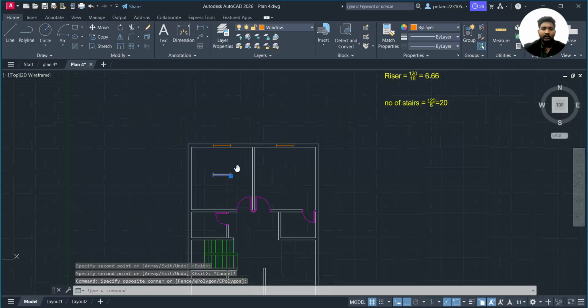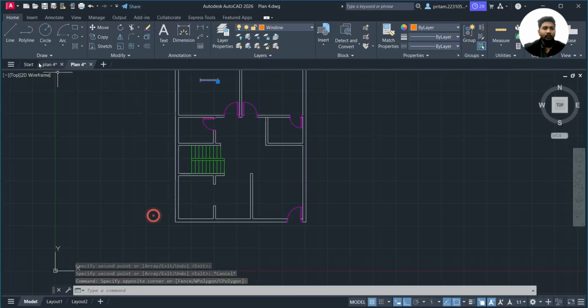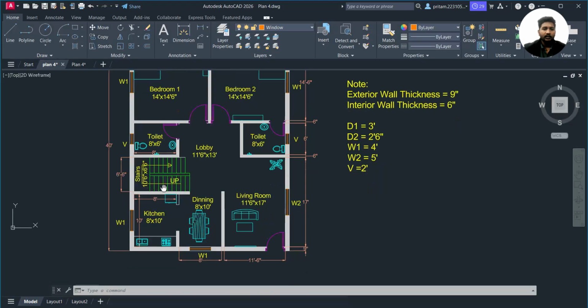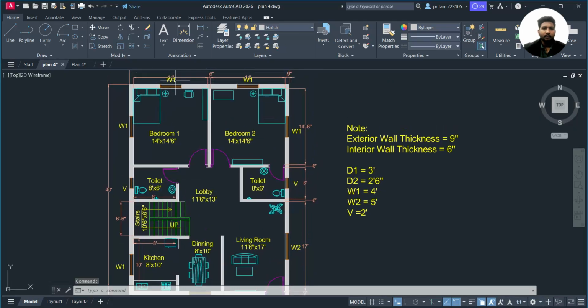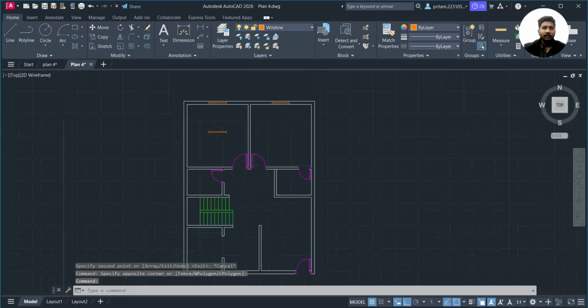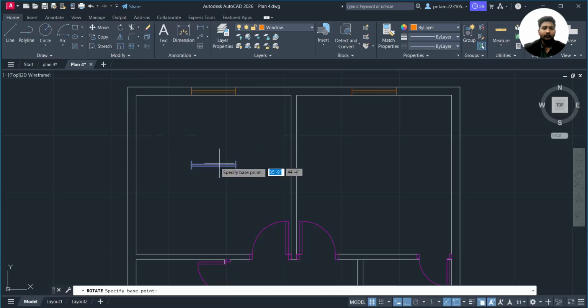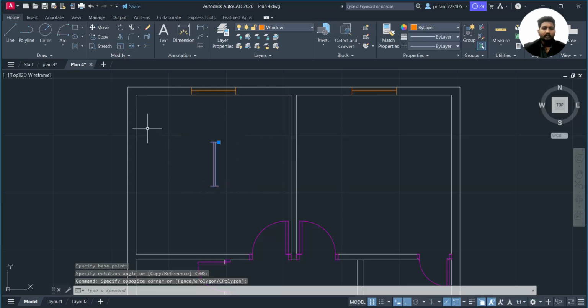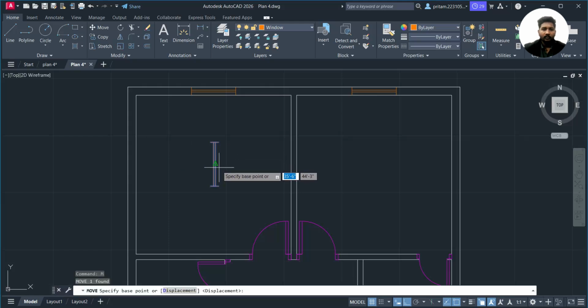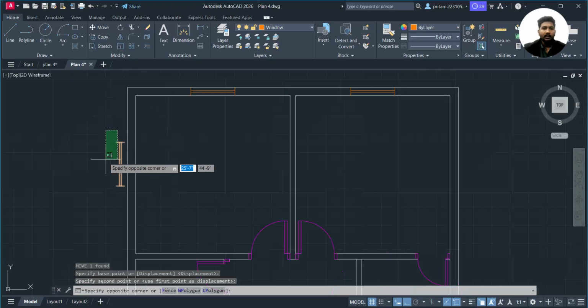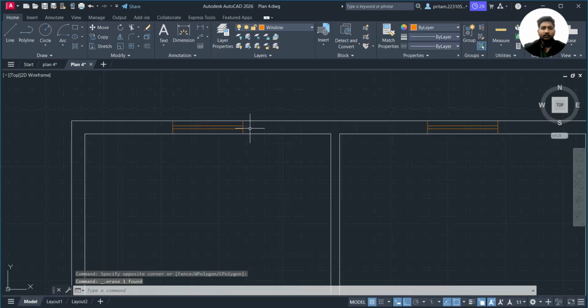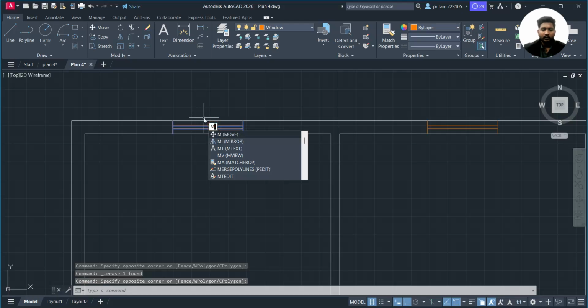Then this orientation is complete, and here no window is present. You can see here that no window is present in this orientation. We have to make it into a perpendicular 90-degree format. Go to your plan. In it we choose this window in the block format, and then rotate it perfectly from the center, with Ortho on at 90 degrees, and it has been rotated. Then we choose here the midpoint, and you can directly delete it first, and you can directly choose from here also, mirror it or rotate it.